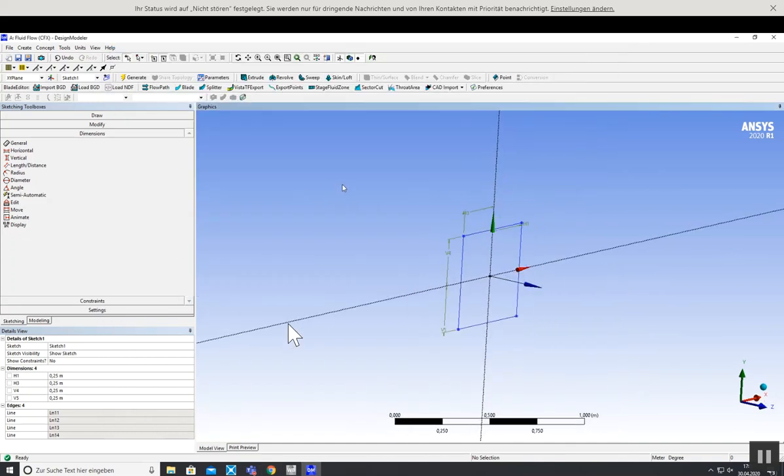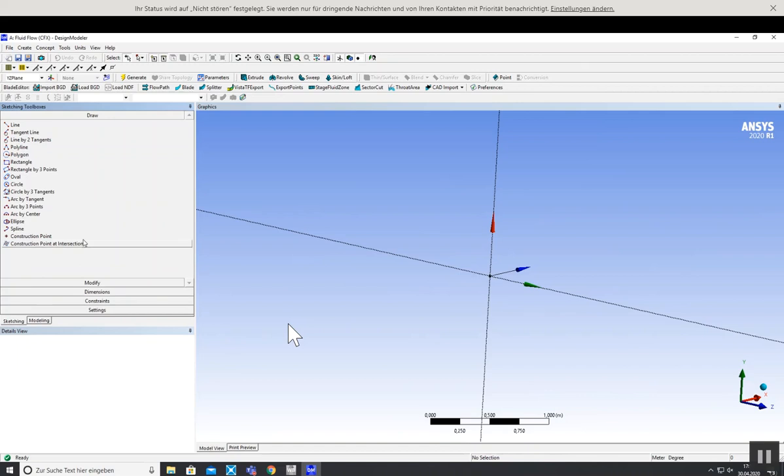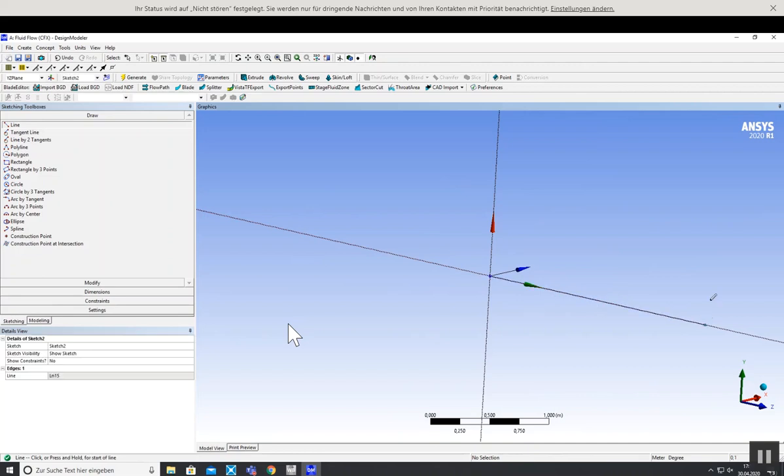Okay, so I do this first step. I go back to modeling and I choose another plane. For example, the YZ plane is really convenient now, and what I need now is a line for the path. The path I want to choose for my pipe, and before I do it detailed, I draw it a bit with a pencil and make sure the pencil head is always connected here.